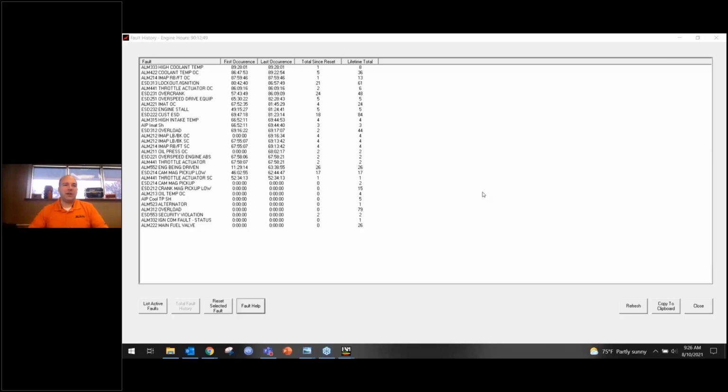Well, then we run a little bit longer. That air charge being hot starts making its way through, and now it starts making its way into my intake manifold. Well, now my intake manifold temperature goes high. And guess what this same customer decides that they're going to do? They say, well, if I can't trust the cooling temperature sensor and the engine's still running, I'm just going to go ahead and disconnect that intake manifold temperature sensor too, because you can't trust those sensors, those newfangled computers. They just don't know what they're doing. So he does that as well.